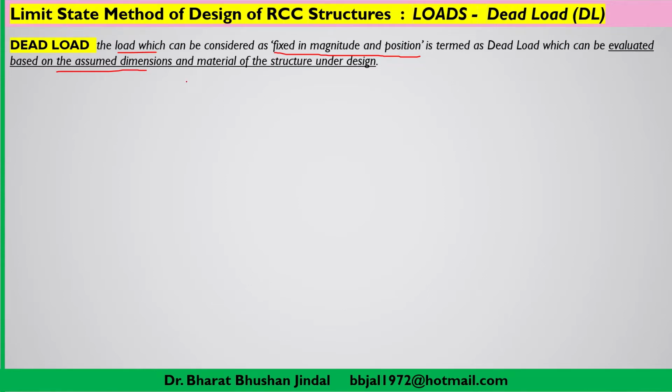That means when you are going to design, suppose, an RCC beam, first of all you do not have information regarding the cross-section dimensions of the beam. So in the design steps, you will assume some value for the cross-section dimensions of the beam. According to the assumed dimensions, you can work out the self weight of that particular beam or section.